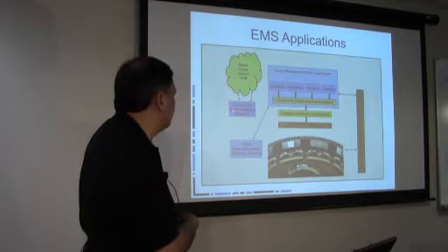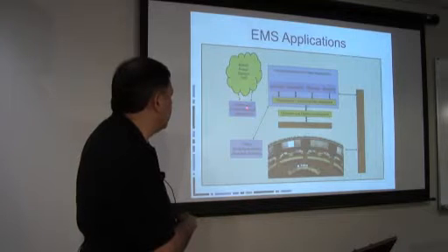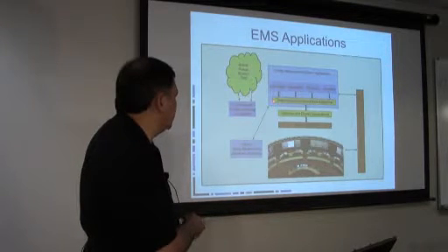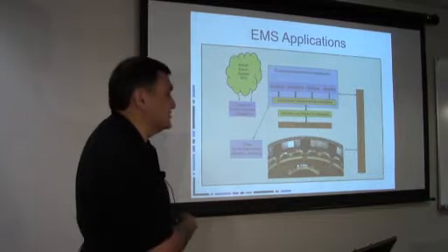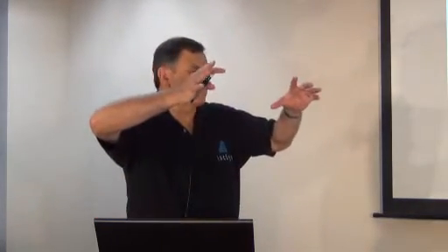So the actual data is coming in from the remote terminal units that I mentioned we covered in the previous session. Those are monitoring the actual power grid, and they are sending their data into the supervisory control and data acquisition system. There may be data links to neighboring utilities, because not only do they need to see the awareness of their own system, it can be very important to see what's happening on their neighboring systems. And then, of course, the top-level reliability coordinator, they will typically have data links to all the underlying transmission operators. The top-level reliability coordinator is just a monitoring function, an advisory. They will not be actually doing any of the supervisory control.